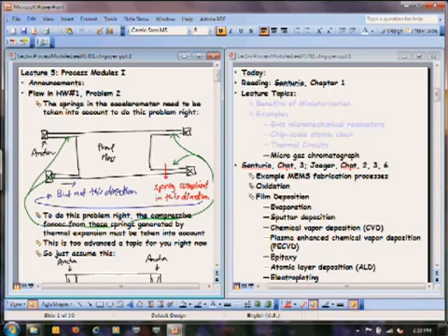So problem number 2, we have an accelerometer. And it's an Analog Devices type accelerometer, so it's got a proof mass that looks like this. This was in your lecture notes and in the module as well. And so that proof mass is held up by these springs. The problem statement says that the springs are compliant. Well, they are. They're compliant in this direction. But they're not compliant in that direction. And so if you want to determine whether this proof mass is actually buckling, which is part of that problem, you have to include the springs too.